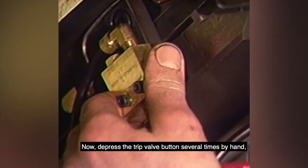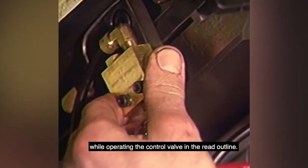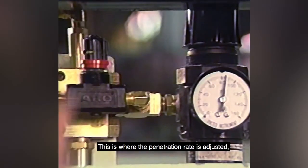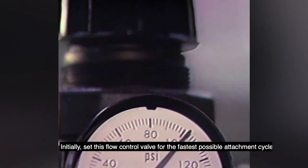Now, depress the trip valve button several times by hand while operating the flow control valve in the red outline. Note that the attachment will cycle faster or slower depending upon where the valve is set. This is where the penetration rate is adjusted depending upon the material being rolled. Initially, set this flow control valve for the fastest possible attachment cycle.